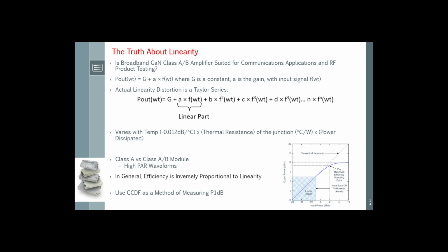And last, you have to see if the right side and the left side of the intermodulation on the spectrum are equivalent in terms of power. If what you have on the left side of the two-tone carrier and on the right side are not the same amplitude, it means that you have some problems in terms of video filtering in the amplifier.